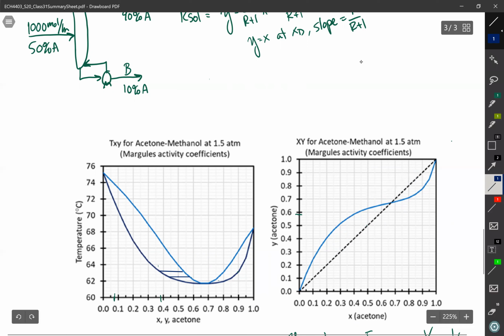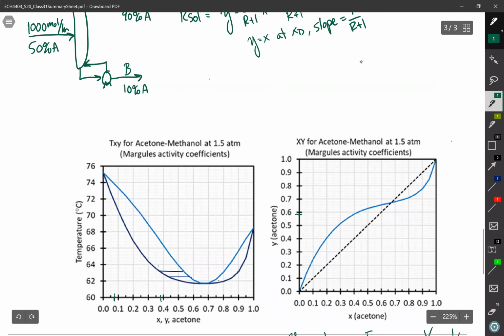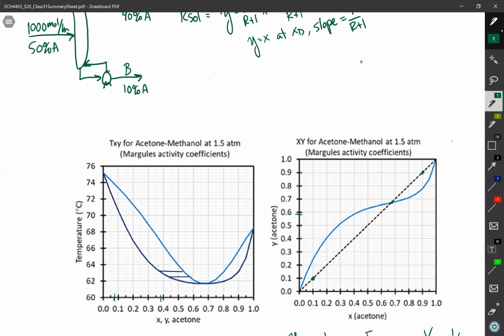Or, you know what? I don't even think it's worth trying to explain how you would go about approaching this. The issue is that I have to have an xD that is on one side of the azeotrope and an xB that is on the other side of the azeotrope. And I can't do that by stage stepping because this represents kind of a pinch point here. If I ever have stages in here, they're going to be way too close and way too intricate. I'm going to need infinite stages just to get there, and even when I do get there, I can't get past it.